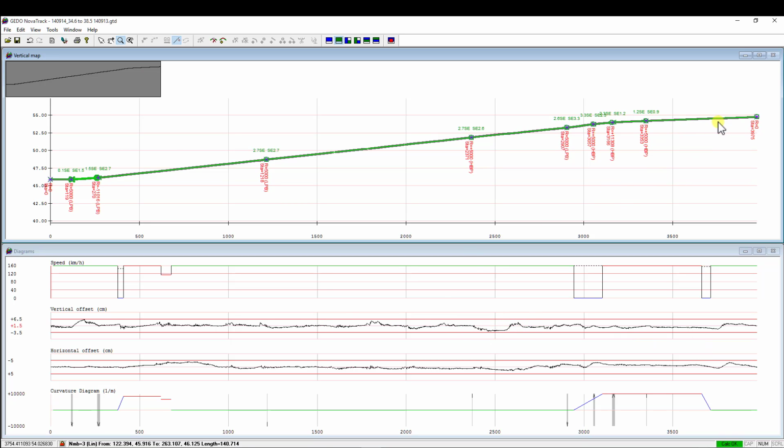The same principle applies to all further editing, adding the breakpoints for the vertical curve. Important here is that each insert angular point is a parabola point, so you can't have breakpoints without a parabola. It should be a parabola. Of course it can be very short, a length of a few centimeters or so.